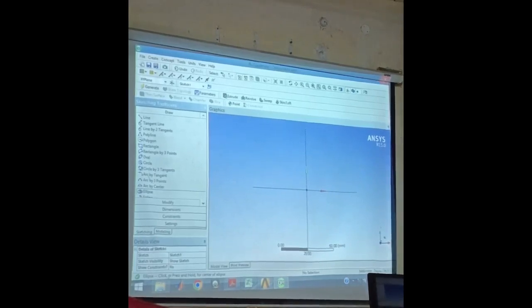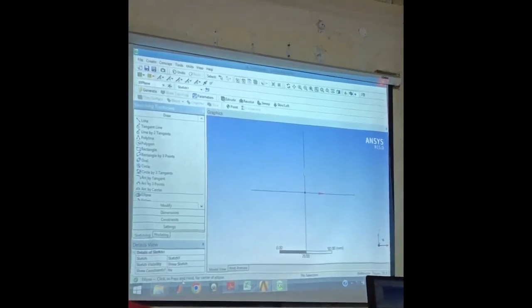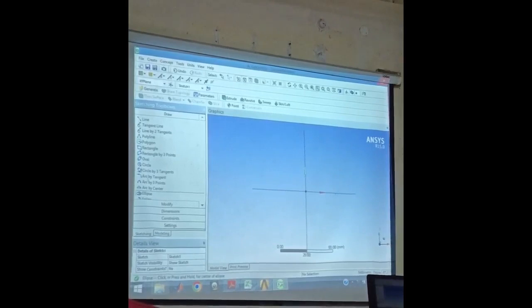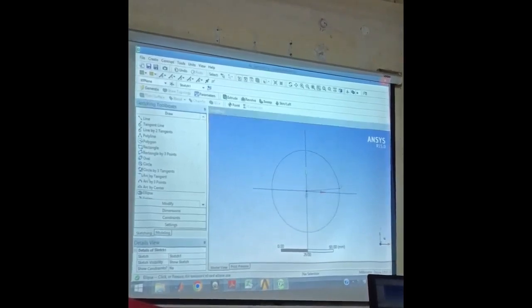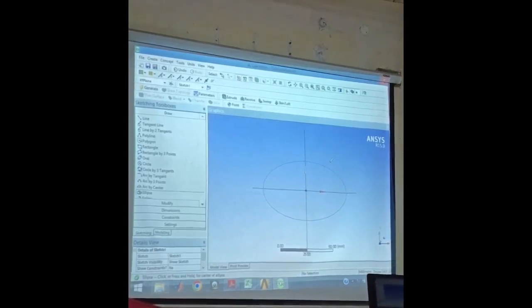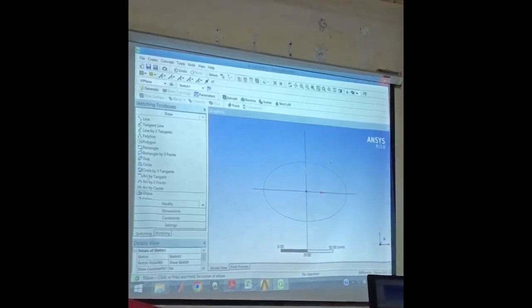To create ellipse, click or press or hold center of the ellipse. So this is the center, P constant. Then click or release for end point of one ellipse axis. This C constant. Then click to indicate length of the other axis. So ellipse has been created. Where center is changed. Semi-major axis, semi-minor axis I have not given till now. I have created the ellipse.